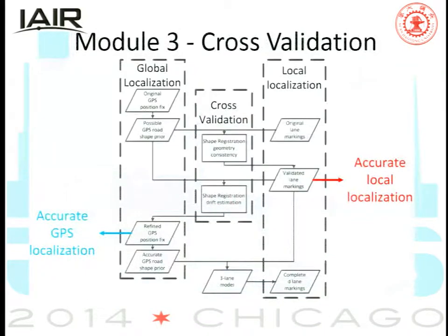However, when the vehicle is driving autonomously, the GPS position measurements may contain shifts from the actual position due to signal masking. Thus, the authors extract a possible road shape prior from the map corresponding to the actual image seen from the camera, and the authors show that by formulating the positioning system in a relative way, they can estimate the vehicle localization in real time.